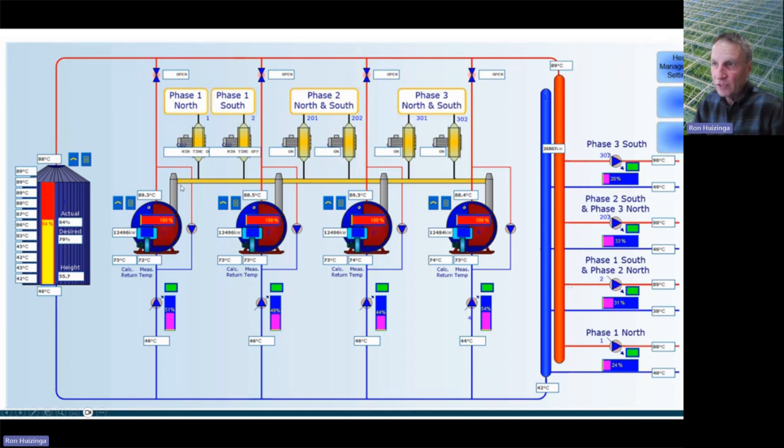So basically the condenser can get too hot if the water going through it is too hot. That condenser is being cooled by this return water from the buffer tank. So as this tank is being filled up with 90, the water coming out of the bottom of the tank here, in this case 42 at the bottom, that 46 here is cooling off that condenser.